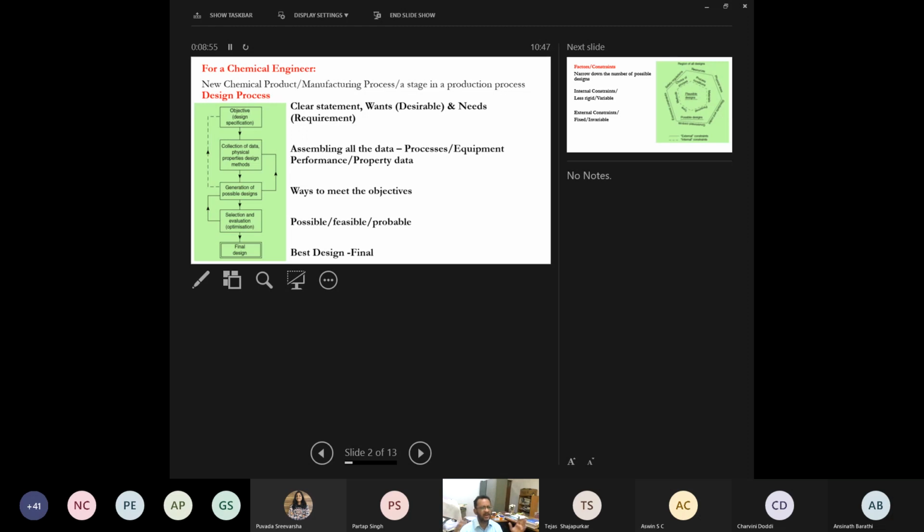When compared to the conventional process, it has around 28 unit operations. Then they did this intensification and integrated the reaction and separation, like azeotropic reactive extraction or reactive distillation.